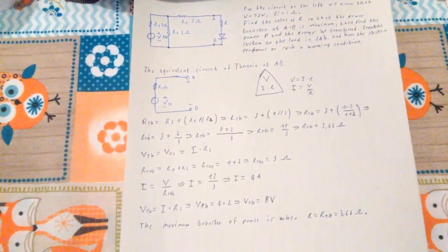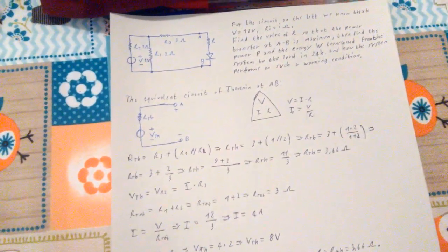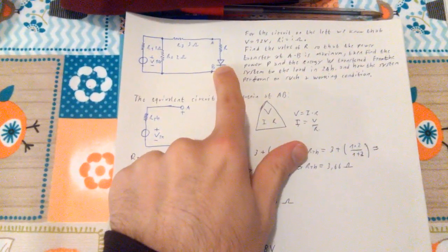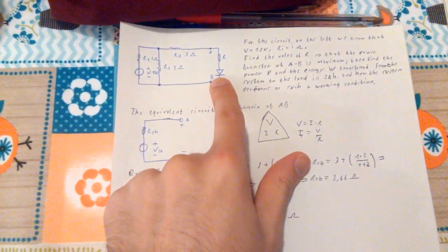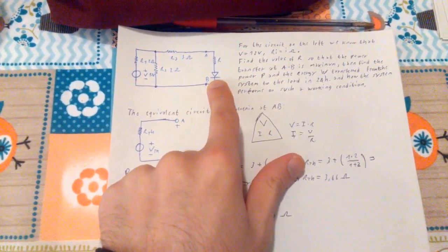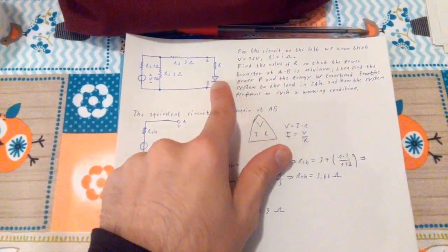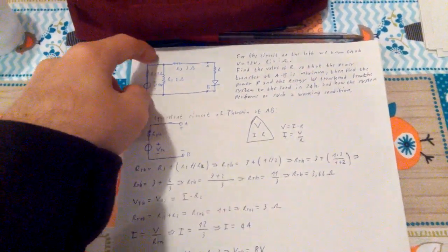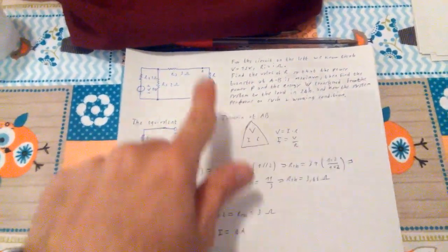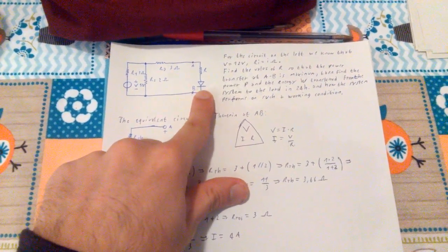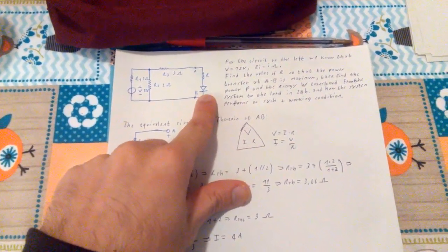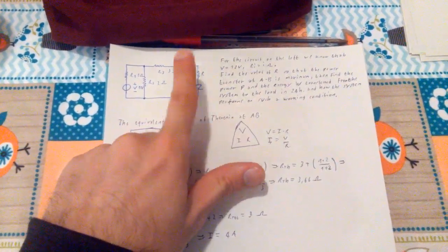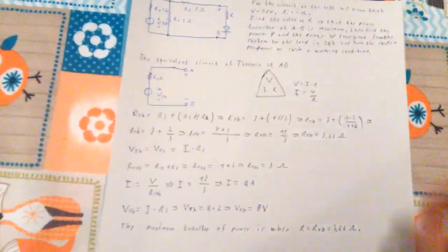So this is looking promising. Now, with all this in mind, we still have the diode here, but this diode, which is an ideal diode, is polarized so that it's going to let the current flow through the circuit. The current is actually going to flow through the circuit this way, so it's going to let all the current go through. And since it is an ideal diode, it's not a real diode, so it has no internal resistance whatsoever, I can replace this with a short circuit.